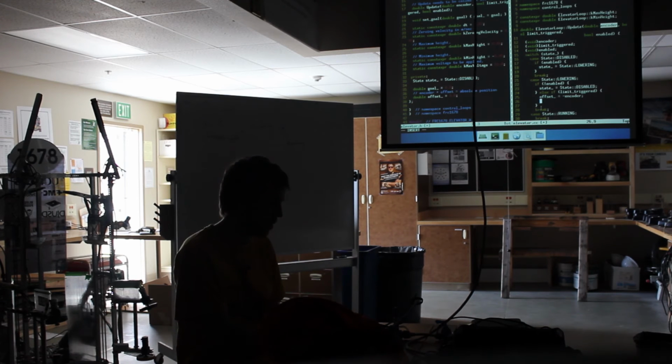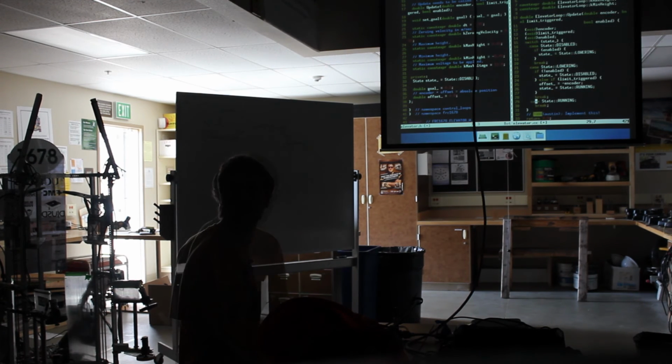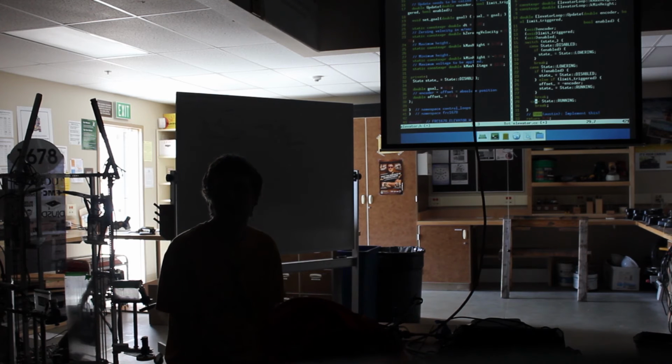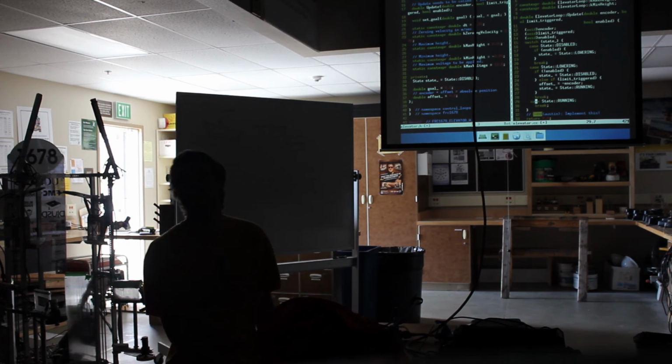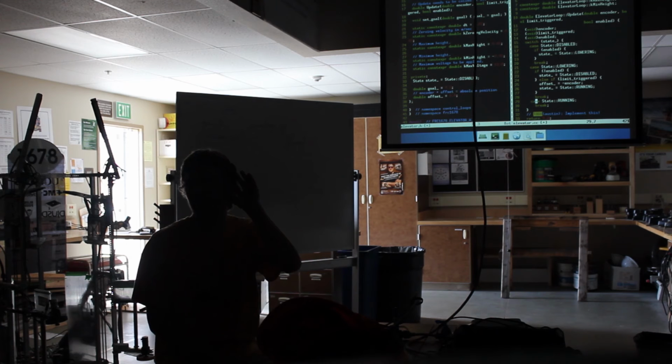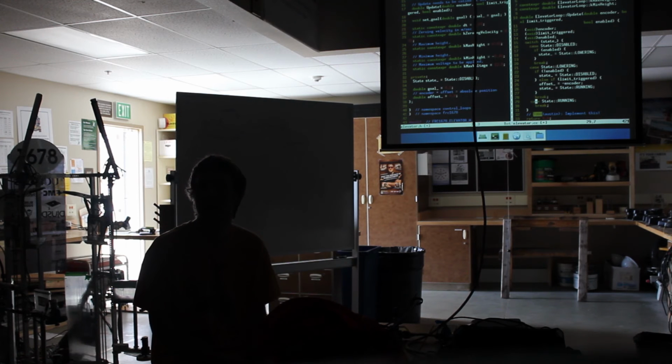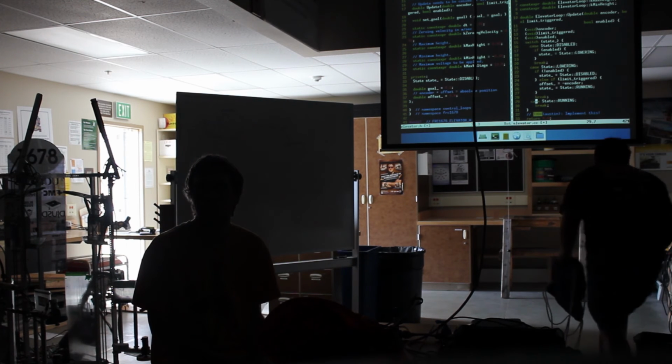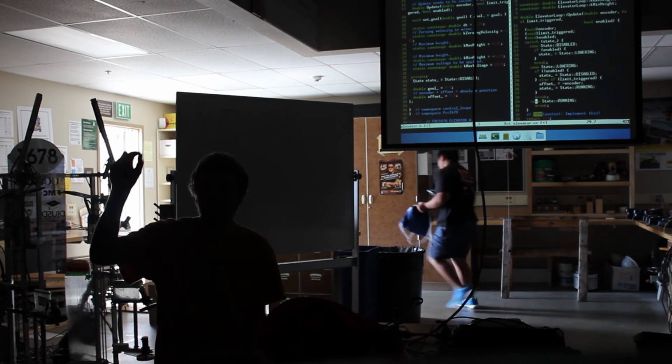Okay, and then we need to change our state, right? If we're in running, do we need to do anything? Wait, I have a question. For lowering, don't we have to start lowering it if we're not? Very good. Okay, so how do you propose we do that? You can return the voltage, but let's be more controlled than that. Okay, so I would propose that we tell our control loop to move down at a slow velocity.